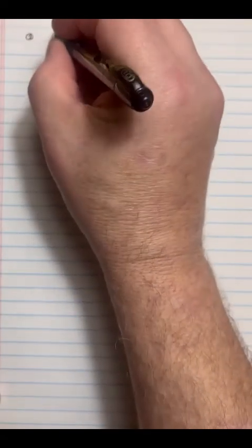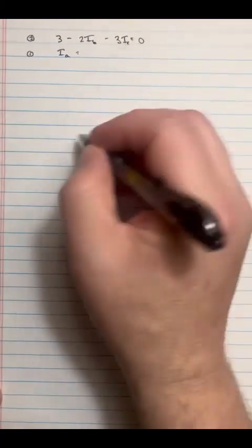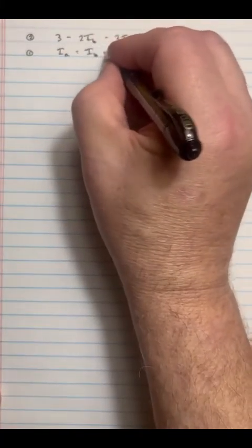So I'm going to go ahead and take equation 2, which was, we'll copy back down, 3 minus 2IB minus 3 equals 0, like that. And let me write down the first equation, which was IA equals, oh, this should be a 3IC, sorry, IB plus IC, like that, okay? And this was IA. Make sure I get this correct, right? That was IA. That's very important to have this correct. That was not IC, my fault. That was IA. You need to make sure I substitute correctly.